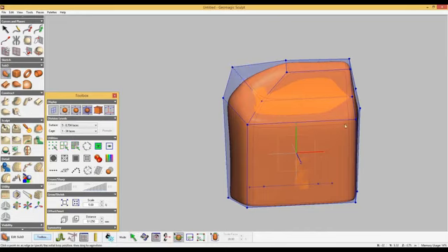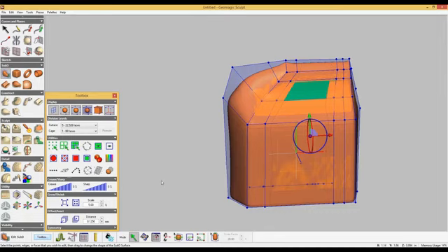Use Add Face Loop to create more control loops around the body of the shape. Grab the Select tool and select the interior face where the opening for the handle will be. Click Add Face Loop. Click the Delete and Fill Hole button, and the handle opening appears.